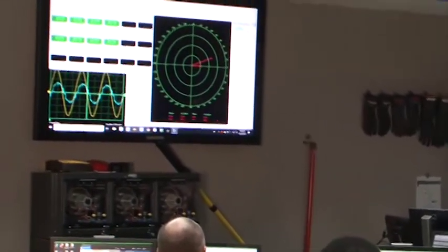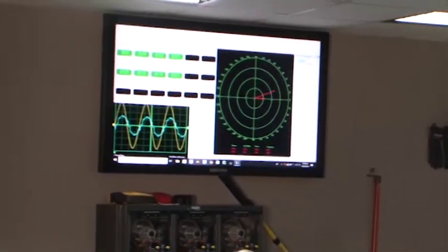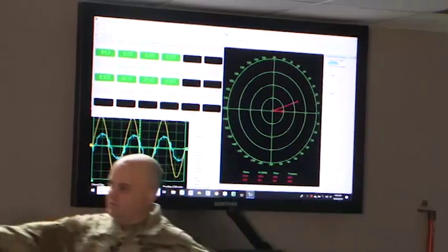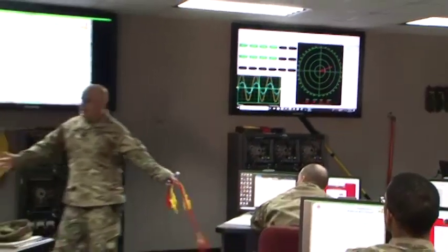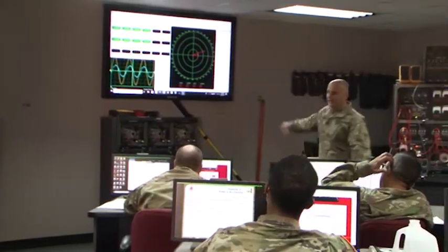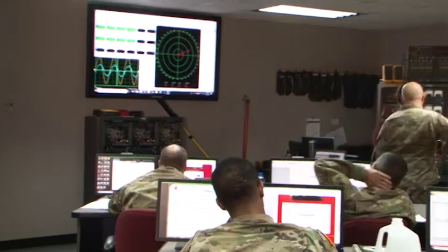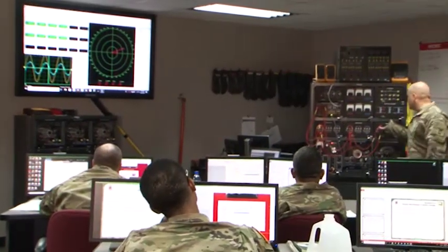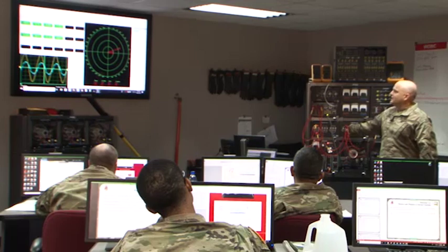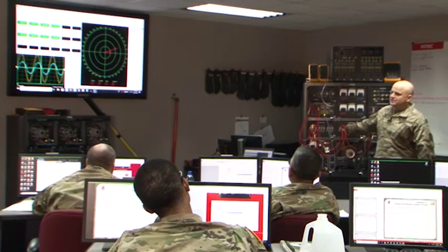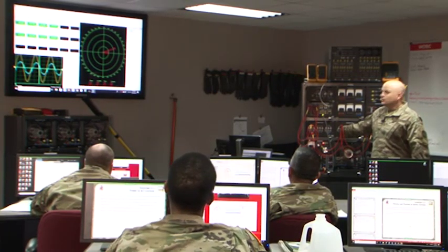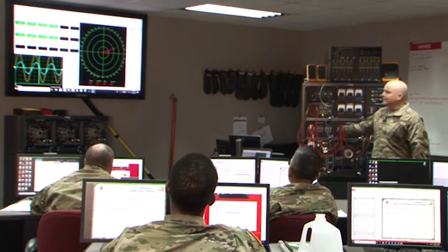Oh. Okay. So by adding some capacitance, I said it was the kid pulling in the opposite direction, right? So again, this is like being at the store. Originally, I just had the one kid, and you still got your weird kid with the leash, right? And then I'm adding another kid over here, who's pulling you over here. Now, based on this, he's not pulling a whole lot. He just pulled a little. And based on my switches over here, I got 2 inductive switches over here, 1 capacitive switch over here. So what if I flip the same amount of capacitive reactance as I have inductive reactance in this circuit? It's going to what? Yeah, closer to 0. All right, and watch what that current vector is going to do too.